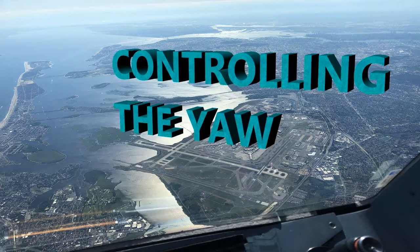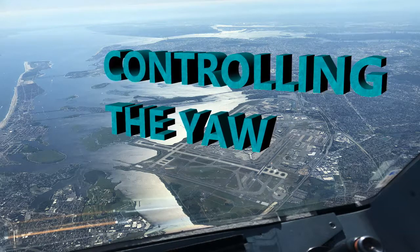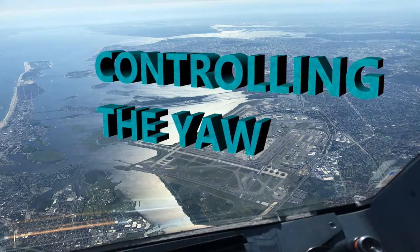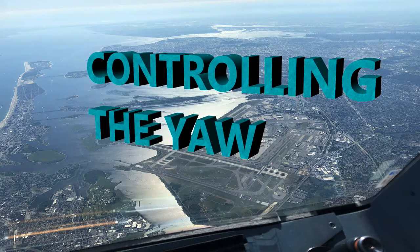Just to reiterate, we do have the 2 computers each, for FAC and for the FMGC. We have this system that is receiving data, but it's also sending out data to other computers that are in charge of certain operations. For example, flight controls, that's one operation. It's going to be sending data to the electrical flight control system, the EFCS. We're also talking about engines, because it can run that automatically and monitor that. It's going to be sending data to the FADEC, your Full Authority Digital Engine Control. It's orchestrating all of this to control both the engines and the flight control surfaces.